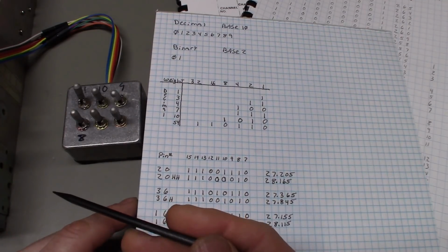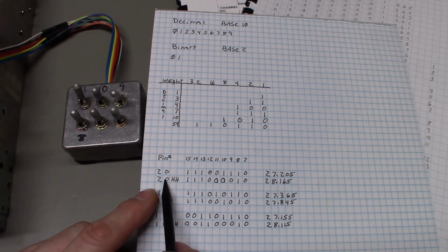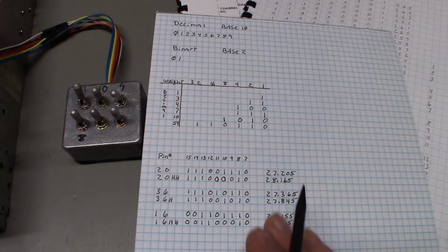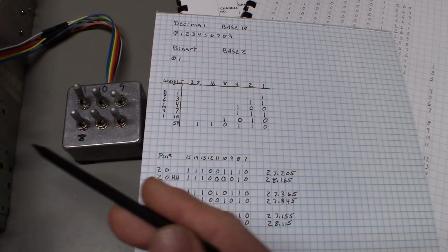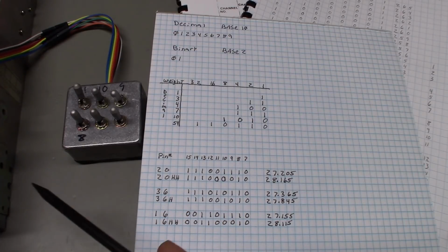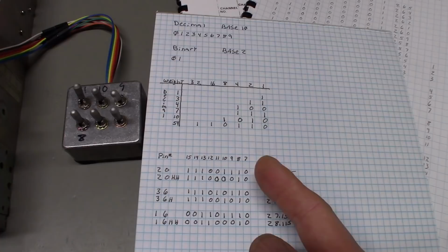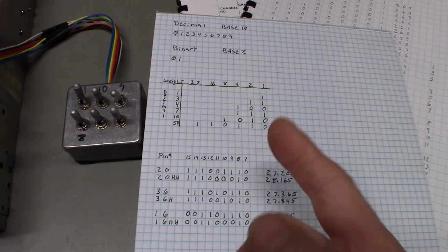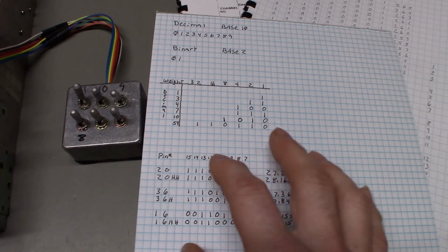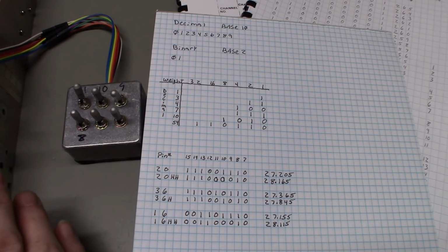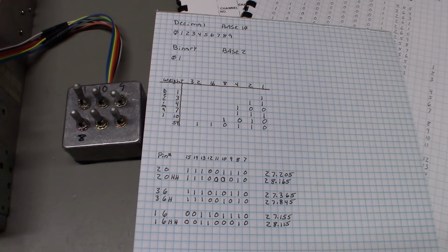If I adjust the VCO voltage to where the PLL, and this is another thing we're not going to get into, but just be aware when you're doing extra channels, remember, the PLL is not the only thing limiting channels in this radio. Getting your VCO voltage and your PLL to actually lock on a channel, well, that doesn't have anything to do with the programming pins. That has to do with the frequency and your VCO voltage, your voltage controlled oscillator, broadbanding, receive, and transmit. Like I say, there's just lots of other things to come into play.